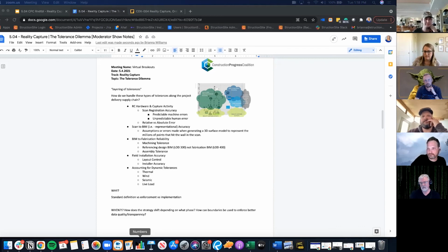We were able to go in and show the wall bow. We tend to take those accuracies a little bit to heart sometimes. I come from the nuclear industry, so just saying that, but there are opportunities to improve. But yeah, I agree with you. Saying something's X accurate sometimes is just dumb because it doesn't make sense. And to put a bow on this, you can definitely prefab from scans and models. It's just understanding how often you need to scan, to what accuracy, and what spot checks.